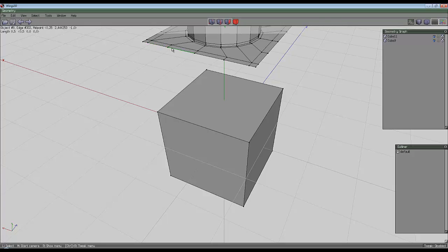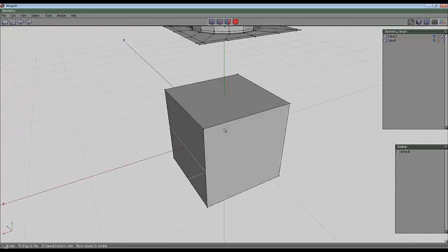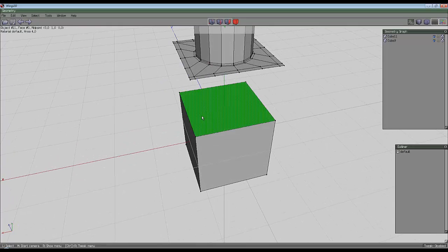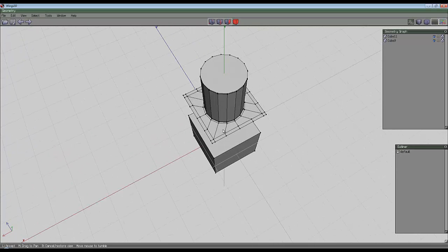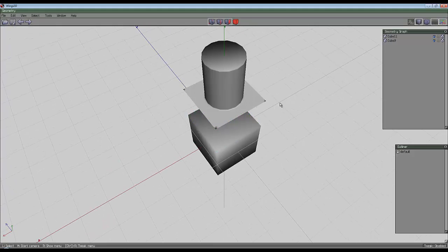Now I could delete the vertexes from this edge and get it to weld then, but we would end up with funny geometry because really we're aiming to have only these quads, these four-edged polygons. That's the ideal situation for sending for rendering, and if you start having things with more than that, called n-gons, then sometimes the renderers can't deal with that and you have strange results, strange shading effects like you have in here, or it's appearing in different places.